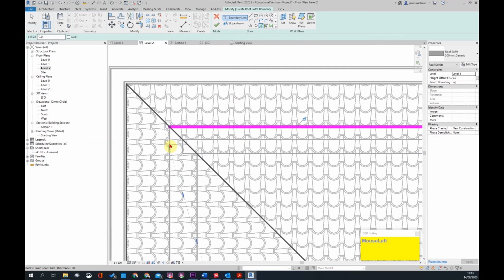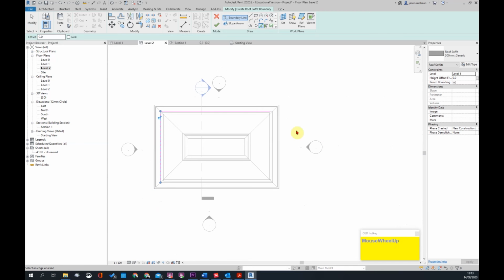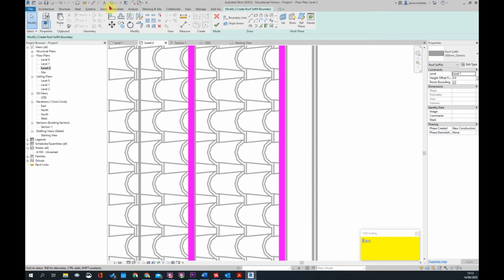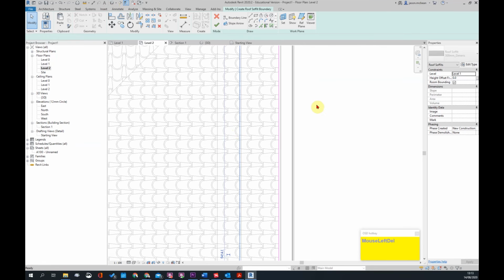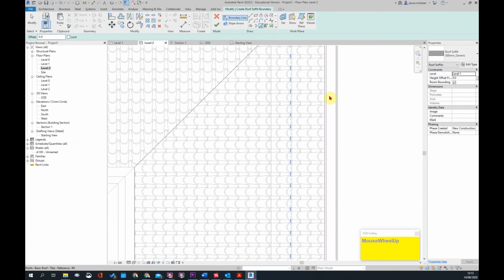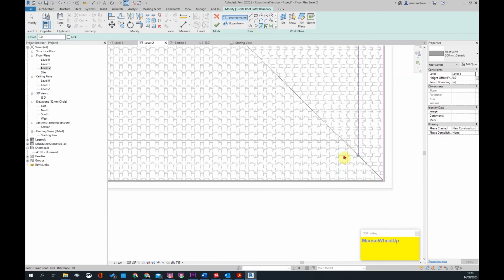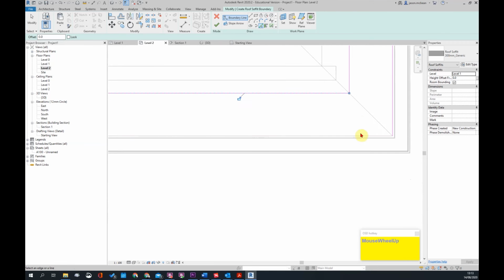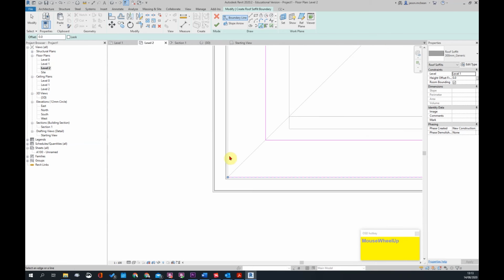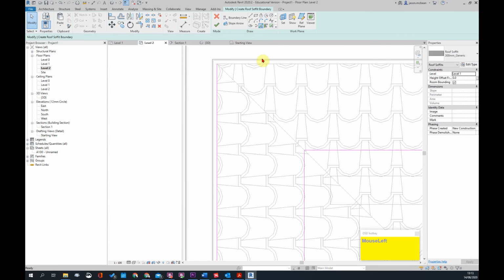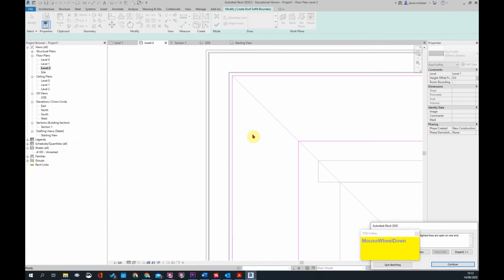Okay, let's say there, I want that side of the wall, I want this side of the wall, I want this side of the wall. Okay, I think it hasn't picked the, so here I'm just going to switch this off. It's picked some strange line there for some reason. Just sometimes with model hatches, it'll try and select the hatch, so that's one thing you're just going to be cautious of. Okay, so there we go. That's all I want to do. And then one more line here, pick line, and you can make them slope as well.